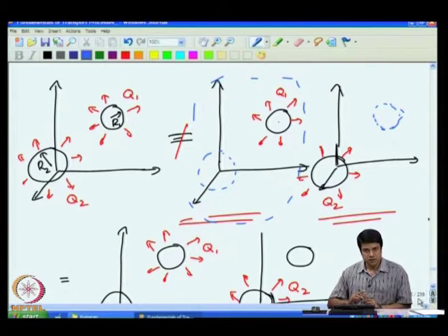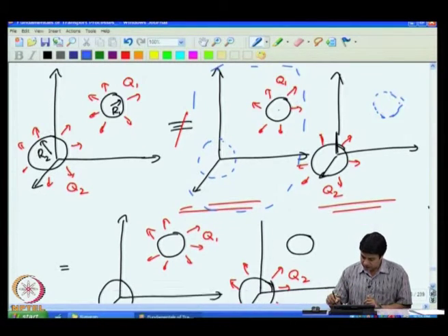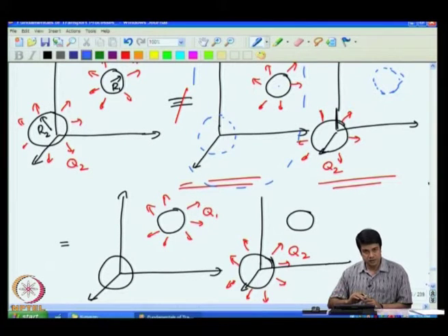It is important to caution that the same superposition principle does not apply for two different particles of finite size. If I have two particles of finite size, I cannot just consider the temperature due to one in the absence of the second and the temperature due to the second in the absence of the first. I have to consider both particles being present simultaneously when I solve the problem, because the boundaries for the two subproblems have to be exactly the same. Okay. However, since the point source has no volume, in this case I can either have or not have the point source. It makes no difference because it does not create an additional boundary in the problem.